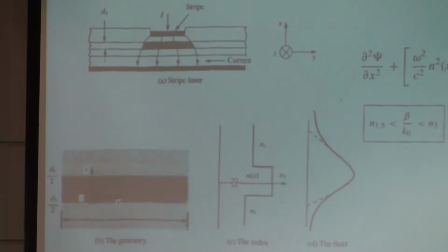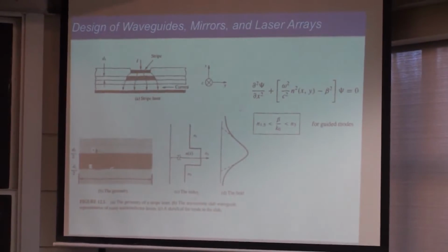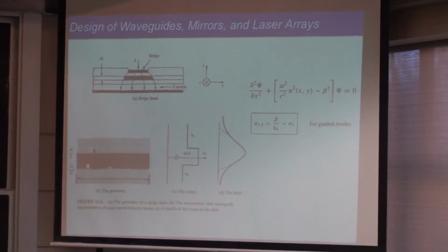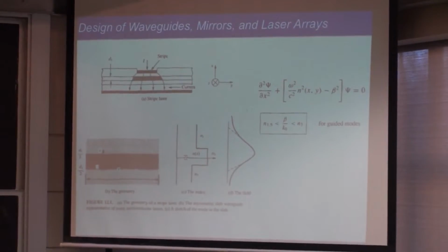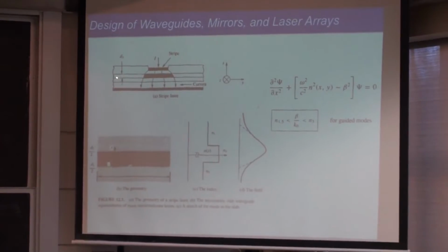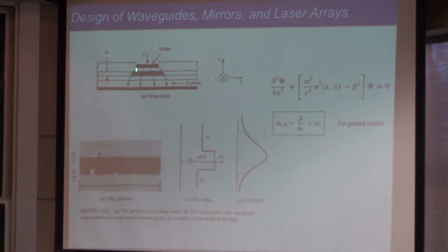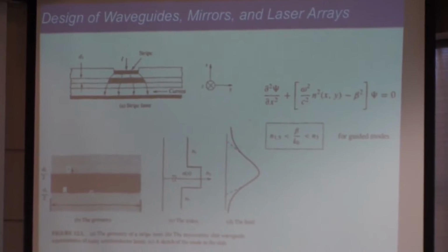Okay. So I will start by just showing a very basic idea of the waveguiding. I've briefly mentioned this a couple of times earlier, but essentially in the laser you have a p-n junction, you have an active region, which is this stripe here, and you're injecting current to push the quasi-Fermi levels Fn and Fp to get gain.